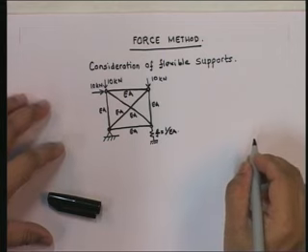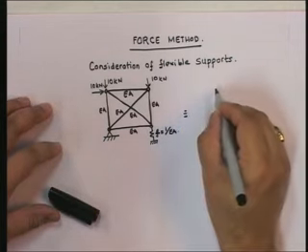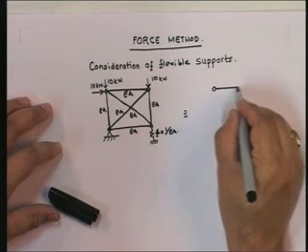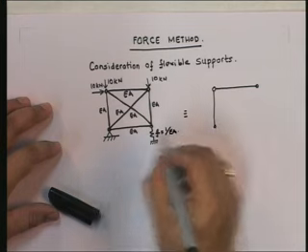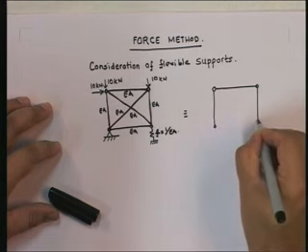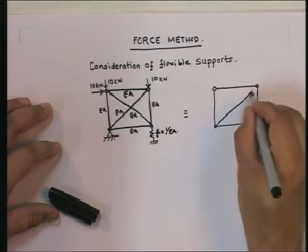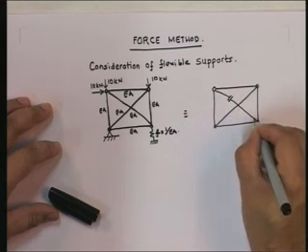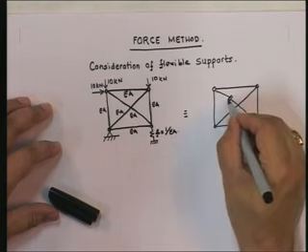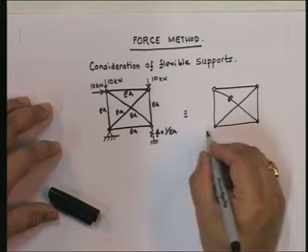Okay. So, anyway, how do we solve this problem? Again, basically the problem goes in the same procedure as last time. You have to develop your statically determinate base structure. I am going to have exactly the same thing as last time. I am cutting this member so that I get a statically determinate structure.